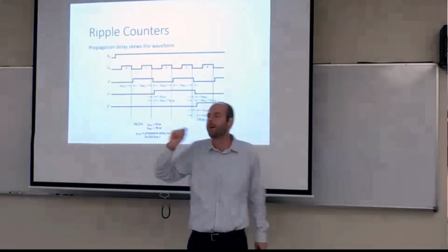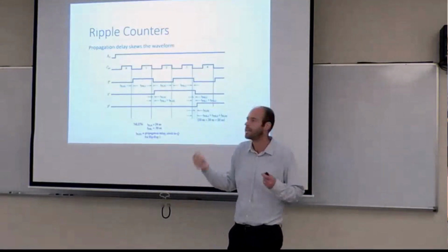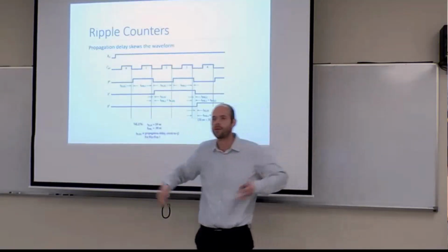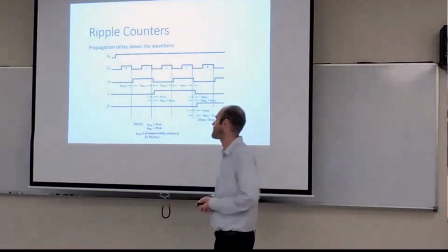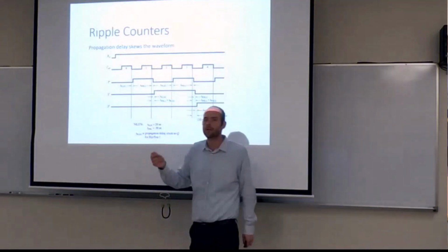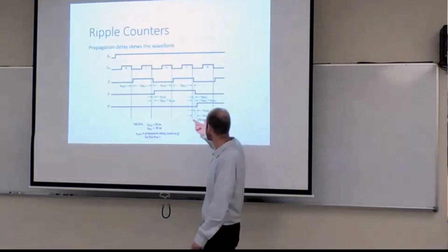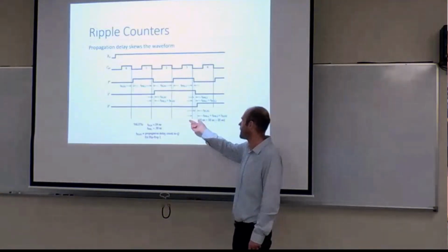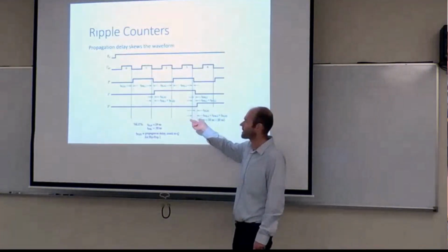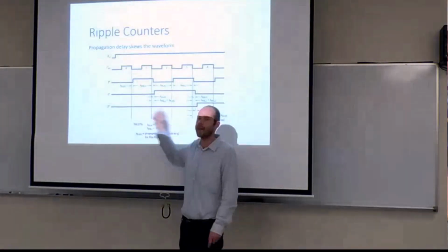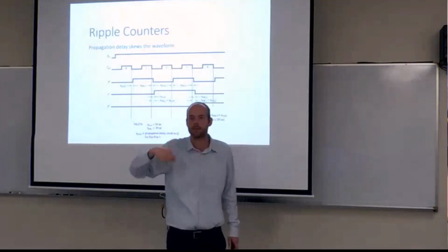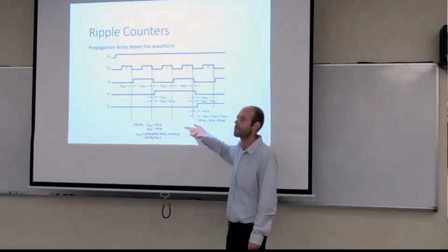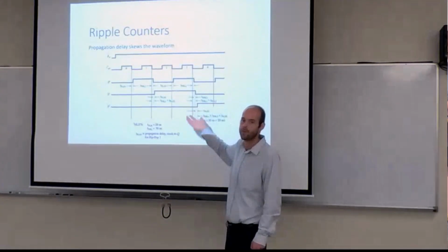So if you have a very fast, gigahertz level speed clock signal, which, if you think about your Intel CPUs, you're at 4 gigahertz clock speeds these days, ripple counters are not appropriate for high numbers of bits. If your highest bit hasn't updated by the time the clock signal hits again, you're in a race condition where you never hit a stable state. So 1 over the total propagation delay gives you the maximum frequency that you can run that system or that ripple counter.